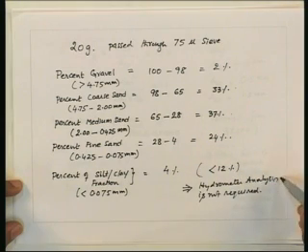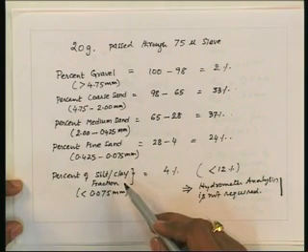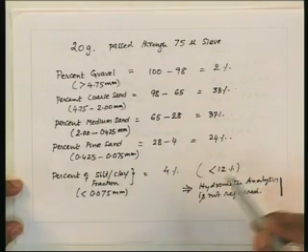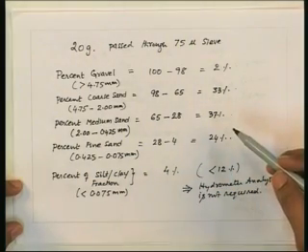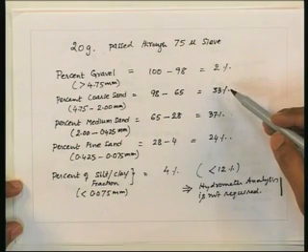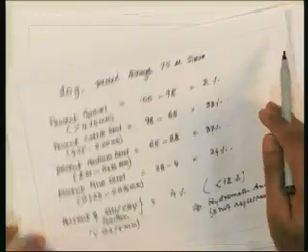As we discussed, the hydrometer analysis is not generally recommended if the percentage of the silt clay fraction is less than 12%, and if it is more, then it is required to be determined and incorporated in the grain size distribution curve. So, having obtained the percentage gravel, sand and silt and clay fraction, we can determine different coefficients which are used for measuring the gradation.